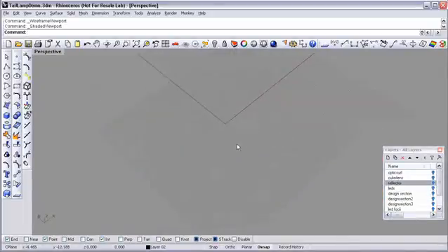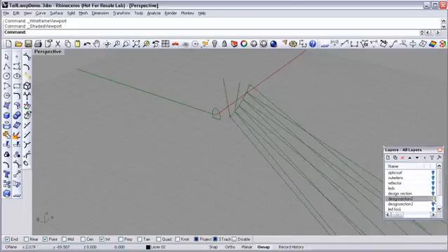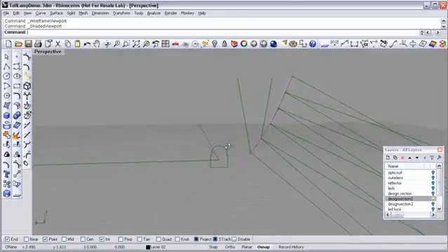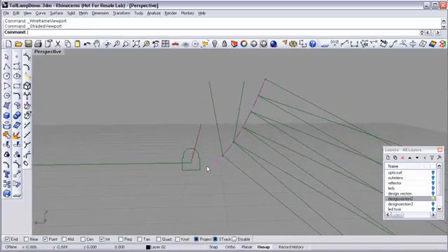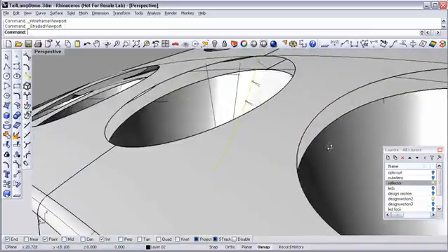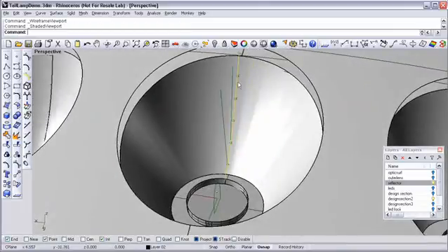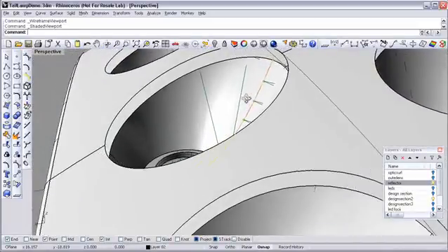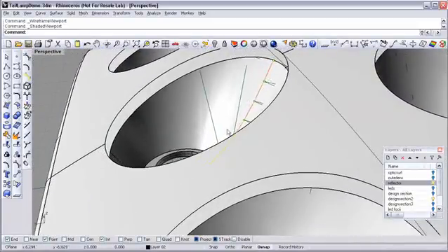So typically when we're designing these types of systems, we'll start with some sort of base shape, and we'll build optical facets onto that base shape. Right now, the line that I've highlighted on the screen is the base parabola. I'm going to turn the reflector back on for a second, and you can see where we're working. We're working in the center cup right now, and I've taken that base shape that they've given us, offset it a little bit, and I'm going to start designing facets into that component.